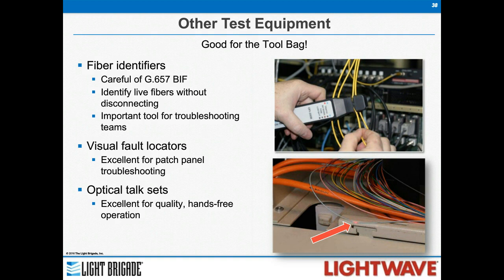So there are a couple in the market that work well. There's one in particular that's designed for bend insensitive fiber. We found it to work well, but don't be fooled that you don't have a live fiber if it might be bend insensitive. So that's a good tool to put in the tool bag.